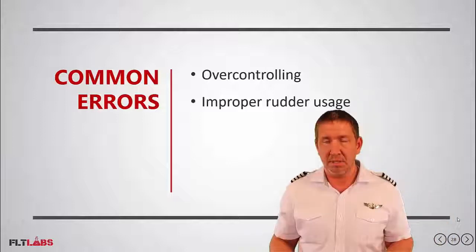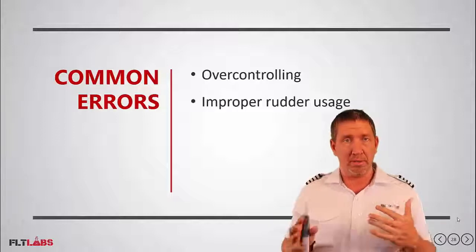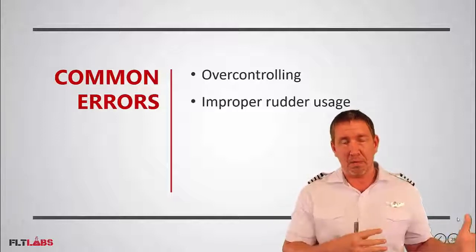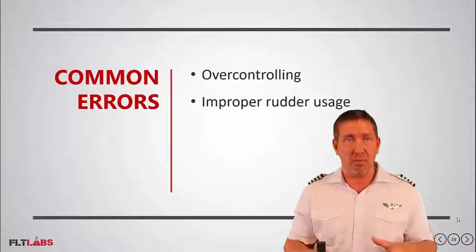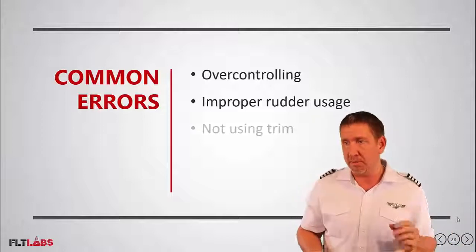Improper rudder use. Definitely the first part of this is going to be not using the right rudder when we're in the climb. Those forces are going to affect us different than straight and level flight. In a climb, we're going to need to add right rudder typically.